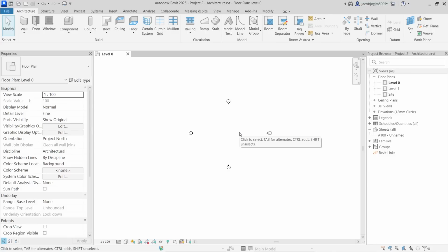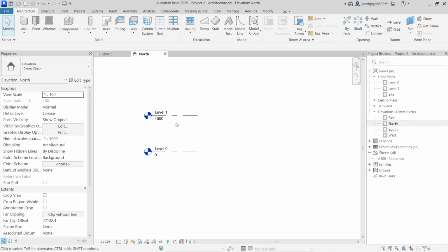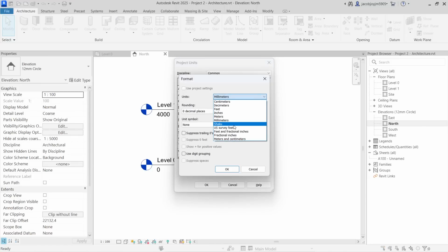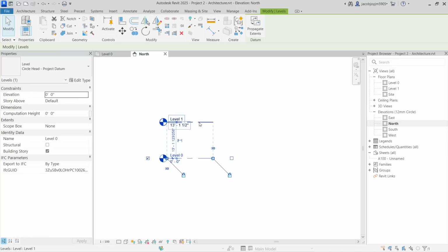So today I'm going to show you till the plinth level. Okay, so site modeling is very important. Okay, let's create a site. So before creating anything, you have to check your levels. How many levels I have and what unit I'm using. I can also use a shortcut UN, and I can go here. I can change it to feet and fractional inches. That's good.